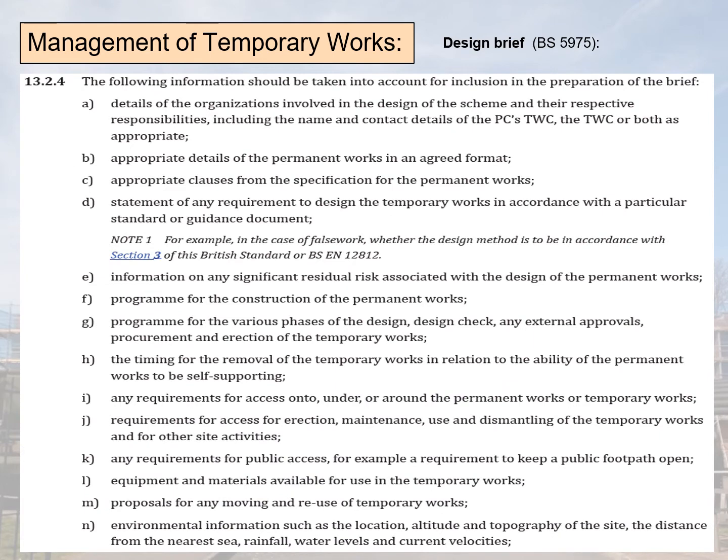Details of any design organisation, including the names of the designers, contact details and their responsibilities, should be included in the design brief. All the drawings for the permanent works, the limitations imposed by specific authorities, including rail, highways, watercourses, local councils and the Environment Agency, should all be incorporated. Specific site and environmental risks should be included, including anything that has come out of the environmental impact assessment.